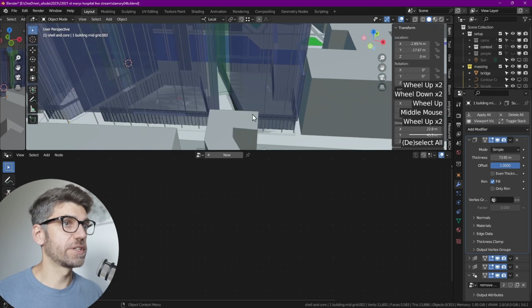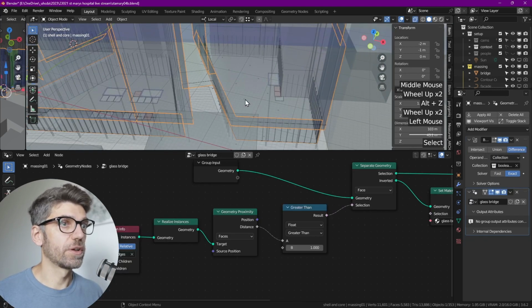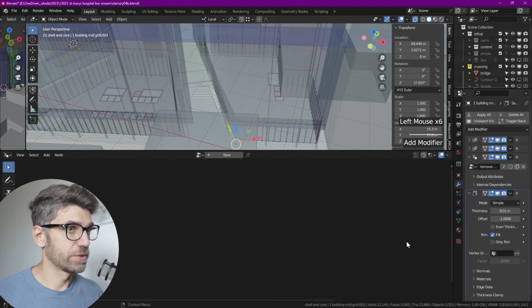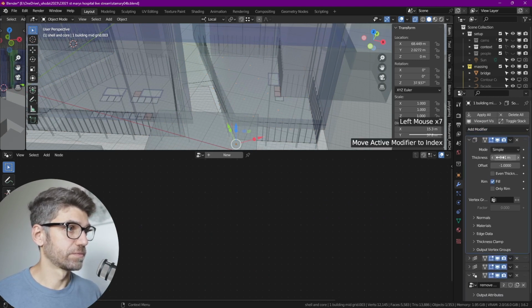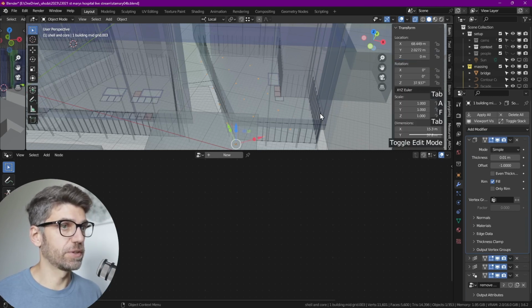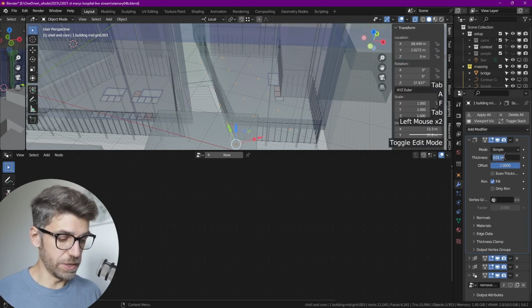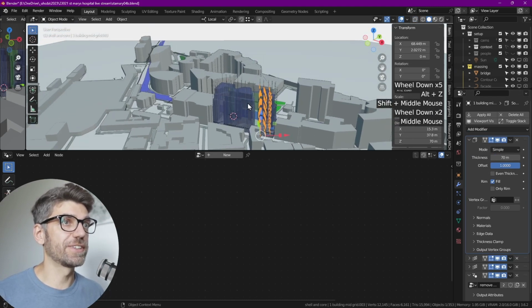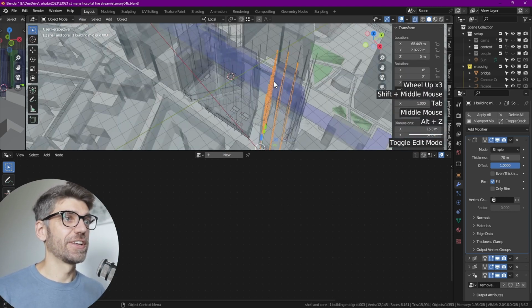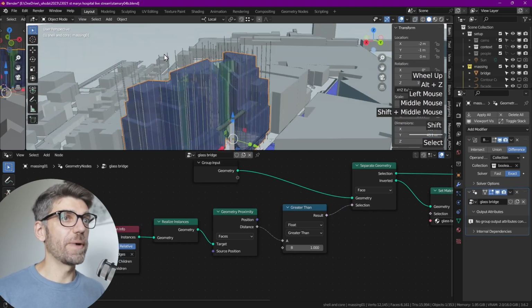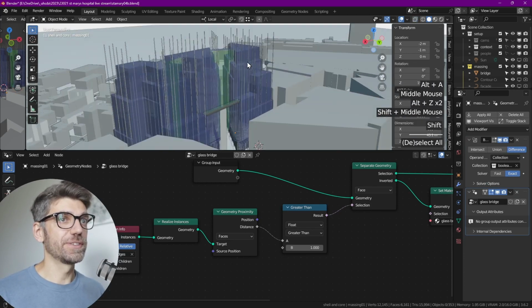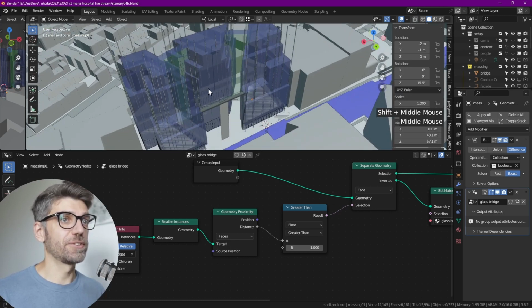And now let's do the same with the next grid, which is over here. So add solidify. Make sure the face is filled, the first one. Offset is 1, and let's go to something like 70 to create a grid. Great, we got a grid. Nice. Now we have to go back and start subtracting a little bit of that grid, right? Let's go ahead and do that.